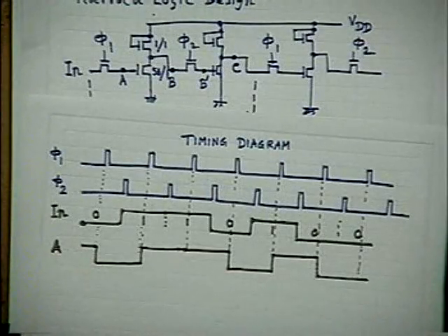But you don't want it here. We want that this drain-substrate junction, which is reverse biased, should give you a very, very low leakage current in order that it becomes a very successful dynamic logic. Therefore, there is a very important thing to keep in mind, that the silicon material for VLSI MOS should be very, very good compared to the bipolar material. In bipolar transistor fabrication, the raw silicon substrate can be tolerated to a certain value.